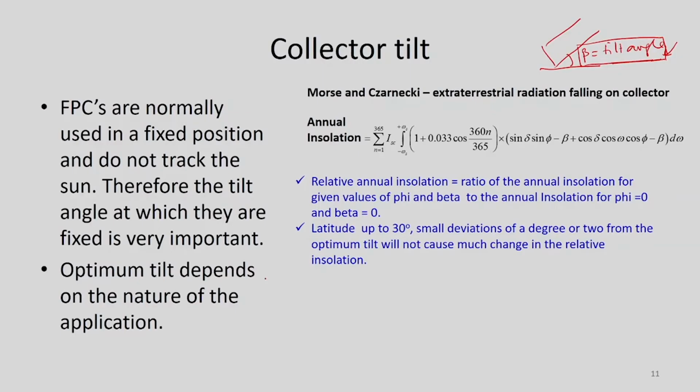So, optimum tilt depends on the nature of the application. This is also important, and there is a host of literature where people have developed many correlations and mathematical expressions which can give the optimum value of beta, or tilt angle, for a particular location.